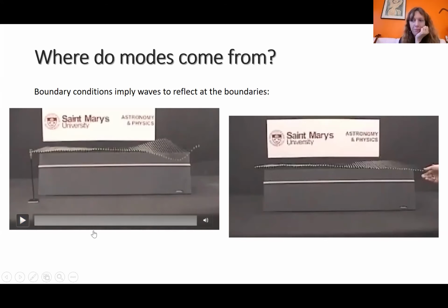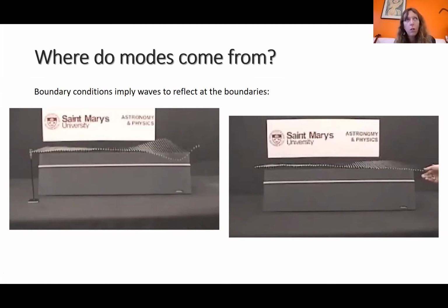Yes, sir. In terms of vibration, yes, it is. We are talking here about the body modes. Any structure's body vibration can be decomposed linearly into different modes. What is not linear in a violin is the excitation process, the stick-slip motion of the bowed string. This is non-linear, but the response in terms of vibration of the body is linear.